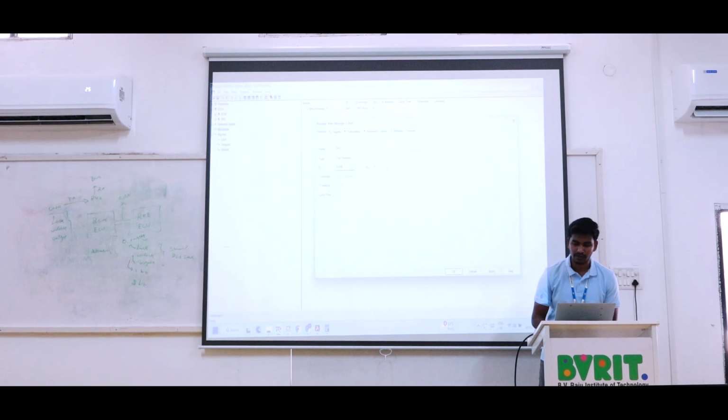So the ID number we have mentioned is 0x400. We can take the type as CAN standard or extended. We are going with CAN standard, so you have no need to change this type. Whenever you open it, by default it will show standard, because initially you open the CAN template only, so it is showing CAN standard. Here you have no need to check anything.